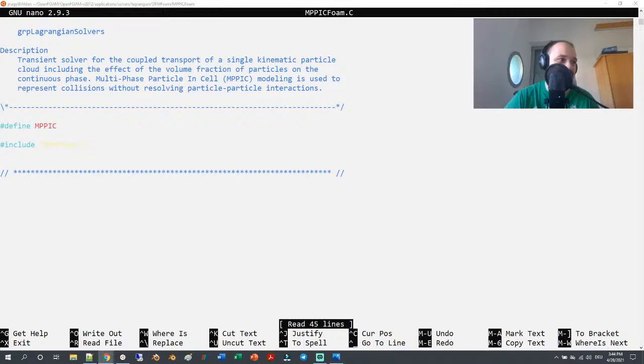Any suggestions on how to check if there is backflow at a patch outlet and quantify how much backflow is occurring? So I would just open the results up in ParaView and load the outlet and then add glyphs, so vectors, and then you can see whether the vectors are pointing outwards or inwards.